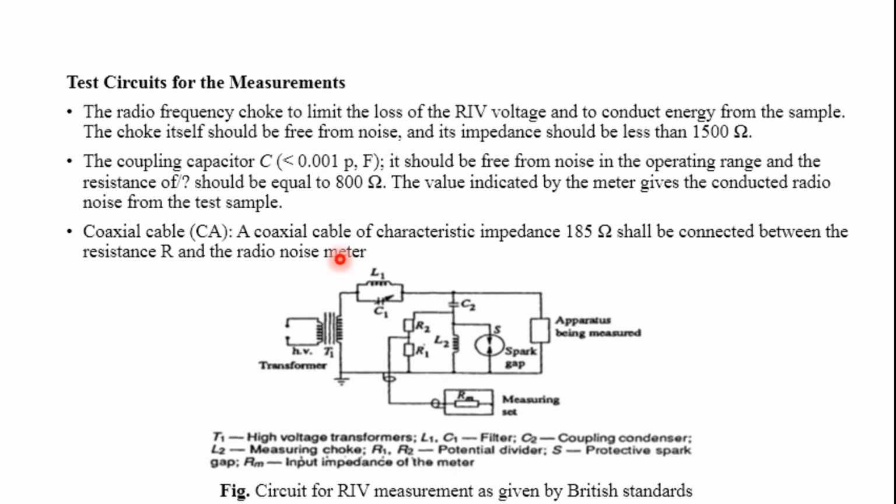When radio noise meter measurements are stated, the information regarding the specification of the meter used, the frequency range of the meter, the band pass characteristics, and the open circuit and detector characteristics have to be mentioned. Nowadays we have transmission systems of 765 kV and above, so radio noise voltages are important, and corrective measures have to be adopted for various apparatus and hardware to minimize radio and television band noises.